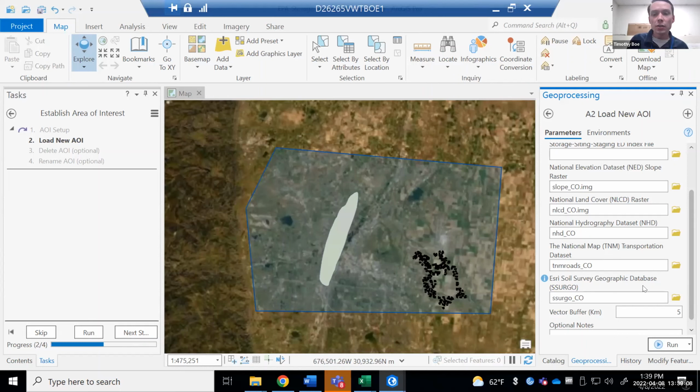The next thing we look at is the soil type. And this is important for a number of reasons, especially as it pertains to chem, bio, and rad. Mostly for rad, in terms of the different isotopes that we may have to deal with. We may want to target specific soils, such as clay soils, so that if you did have an incident where your containment failed and you had some leakage of contaminated waste getting into the ground, at least you could identify certain soil types that would reduce the migration of a given radionuclide.